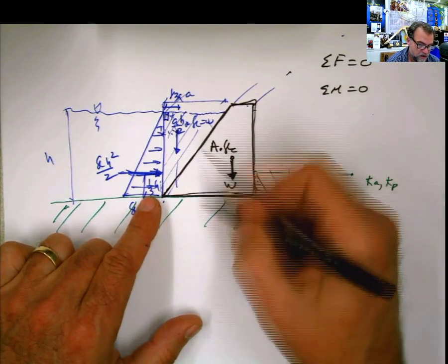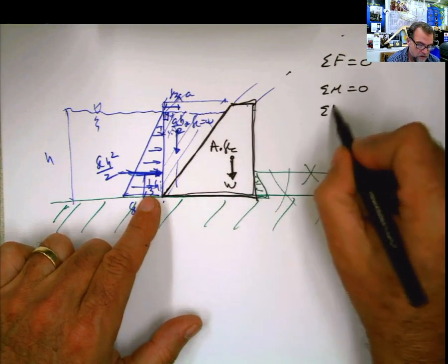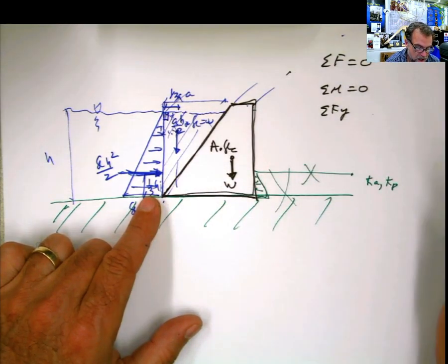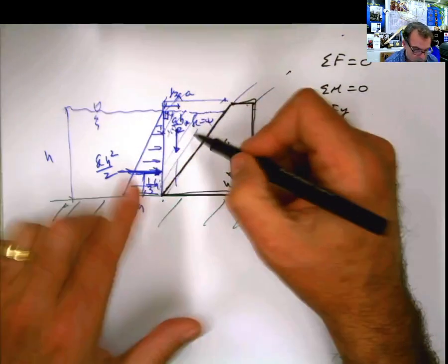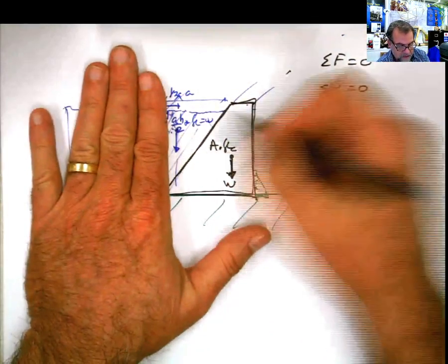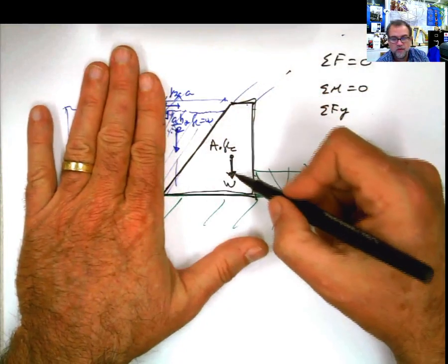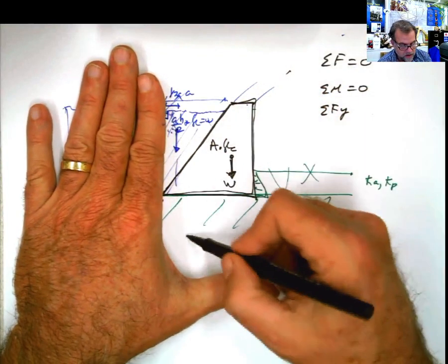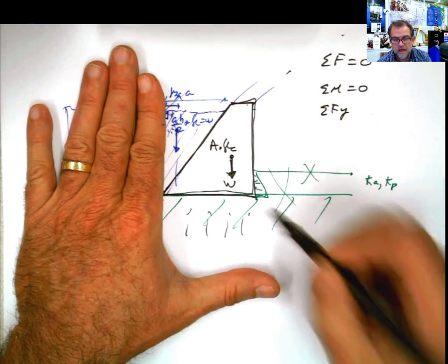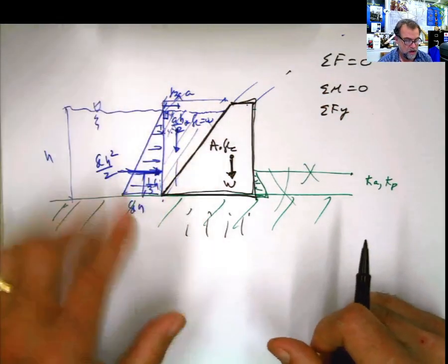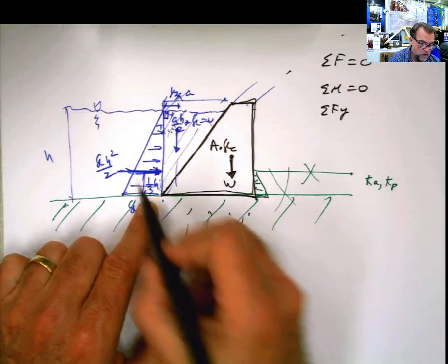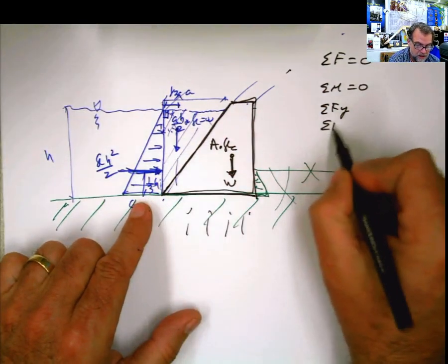Now, what summation of forces? Summation of forces in Y. What forces in Y are acting here? This part, I don't care. But the part acting over the dam, this force plus this force, has to be equal to the strength of this soil so it doesn't sink. You are not at this level yet, but that's one of the reviews that you do. Now, what is the other review that you can do? That the horizontal summation of forces in X equals 0.